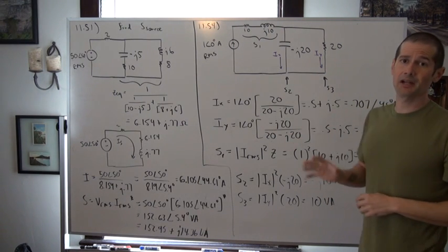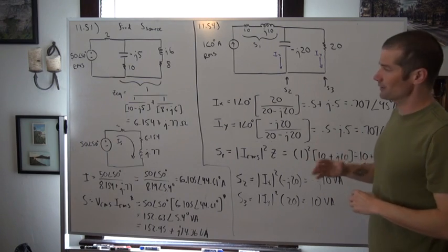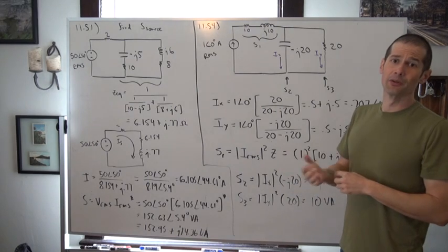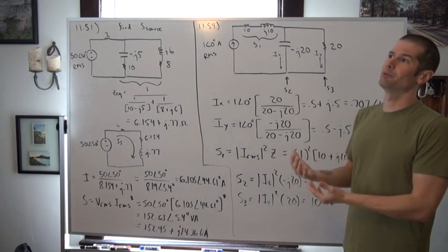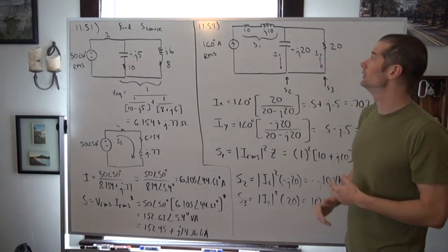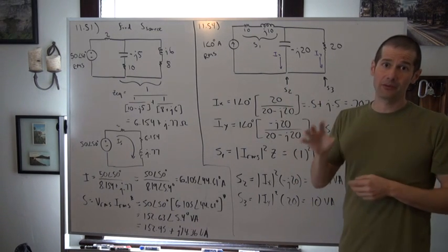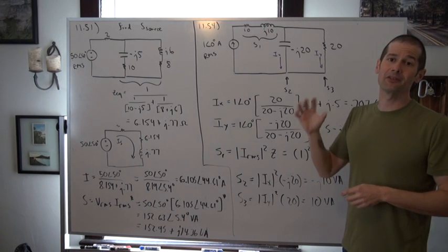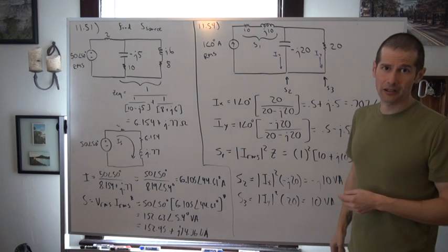Now one thing that is kind of weird about this problem is that when it does ask, or any problem asks for the complex power within any branch, normally we look at seeing that being made up of real and reactive power, P plus or minus jQ. However, when we look at a capacitor, even though we know that a capacitor will have only reactive power in it, we still have to say volt amperes in the event that they ask us for the complex power.